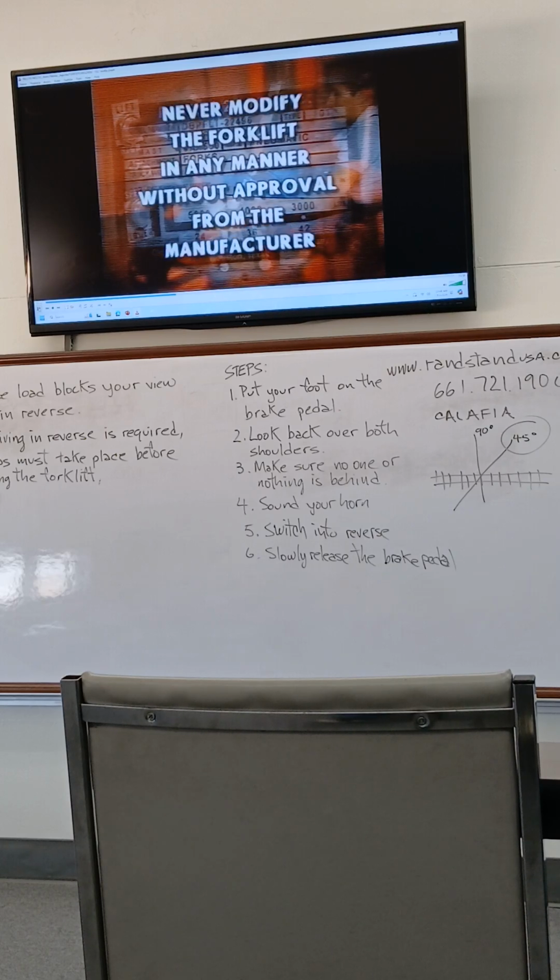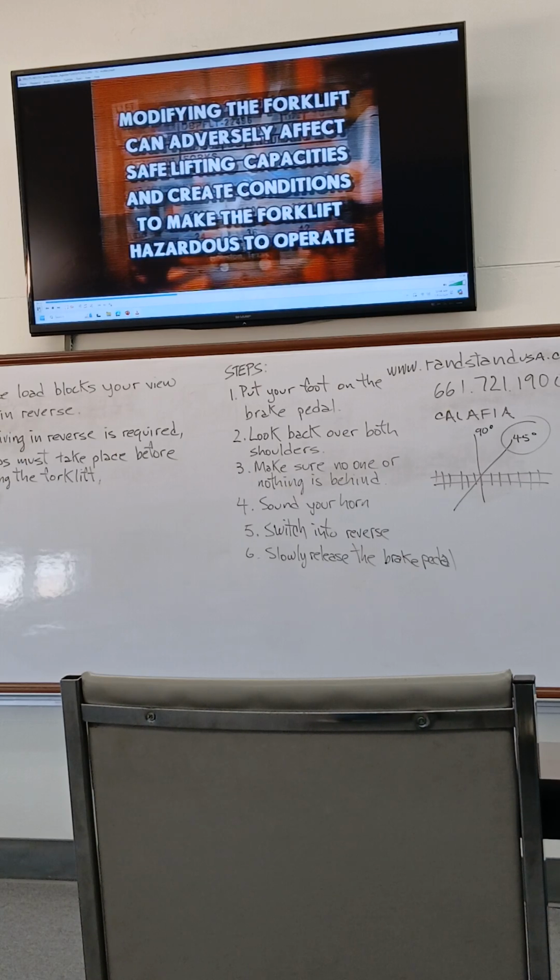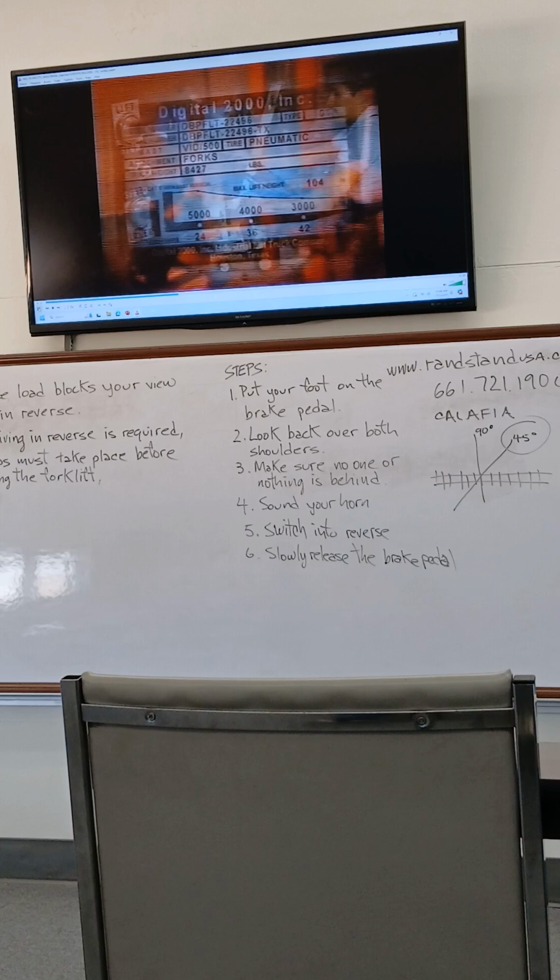Never modify or change the forklift in any manner without approval from the manufacturer. Modifying or changing the forklift can adversely affect safe lifting capacities and can create conditions to make the forklift hazardous to operate.